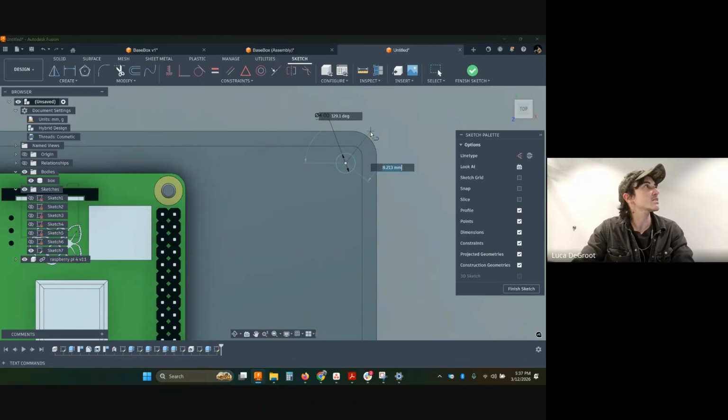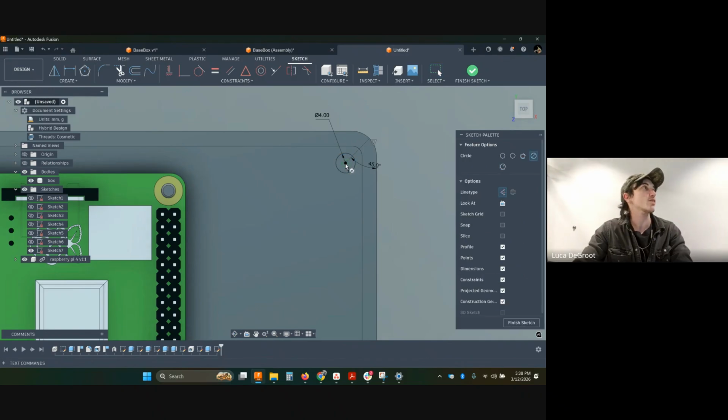I'm going to make this even between these two. So I'm going to use this, make that 45, so that it's always coming out from the corner. I'll start usually with the major diameter, so that I know the thickness is going to be sufficient, because I want to make sure that there's enough meat in there.